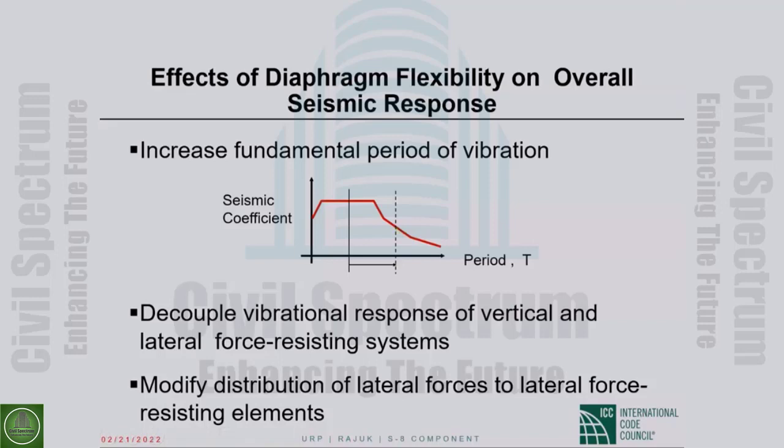That can happen when the diaphragm is flexible. Now, whether the forces will decrease or increase will depend upon the response spectrum of the earthquake that is hitting our structure. But the point is that the period is changing. Also, decouple vibration response of vertical and lateral force resisting systems.